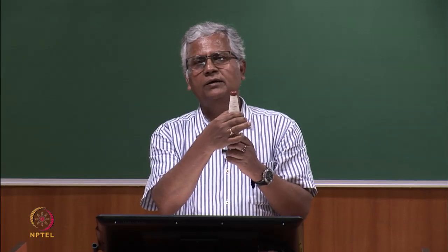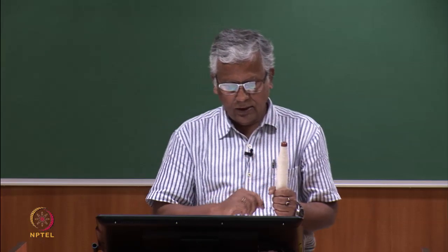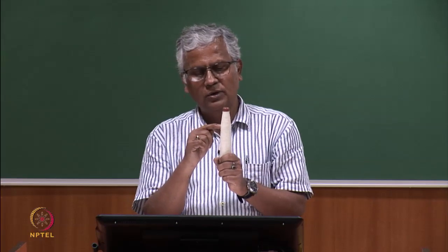If I remove the yarn, let us say from here to there, we will still find a conical part always, because we have generated the conical part right at the time of base building, and then onwards we always had the conical parts. So, whether it is here or there, the conical part will always be there. Now, the shoulder is the part where the diameter is more, and the nose is the part where the diameter is less.